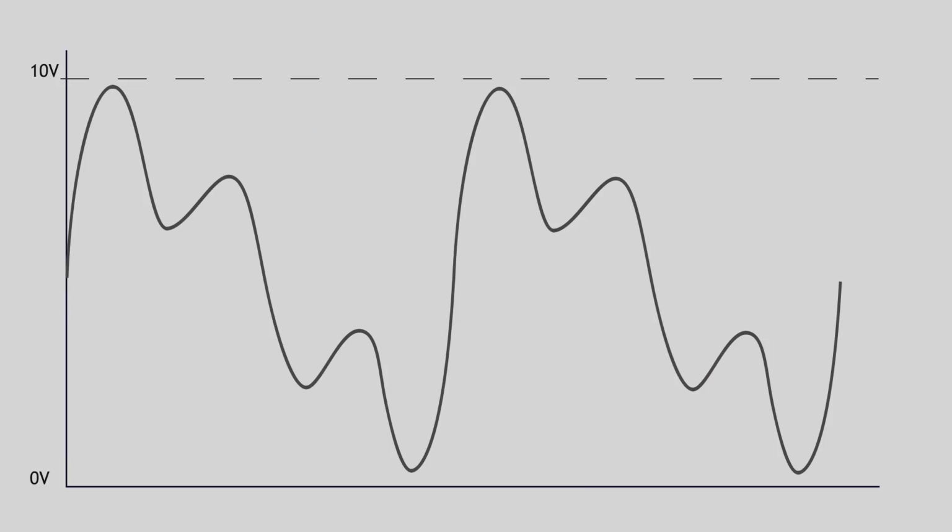Let's say we have some signal, like an LFO for example, and we want this LFO creating 3 separate pitch CVs to control 3 voices. I also want to be able to control boundaries of 3 voltage ranges. For example, the green region would create pitches for the bass voice, the blue region would control the second voice, and the red one would be used for the third voice.